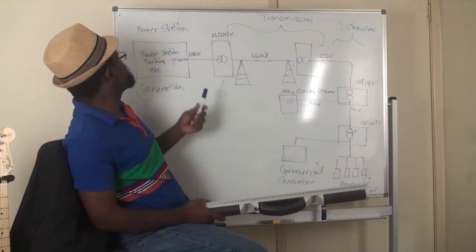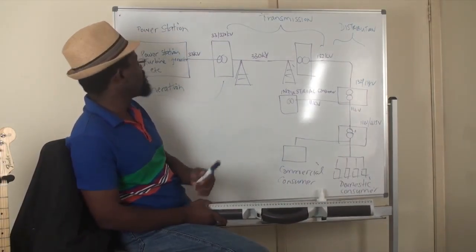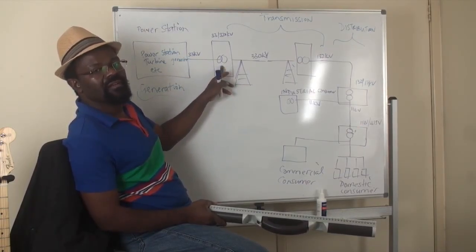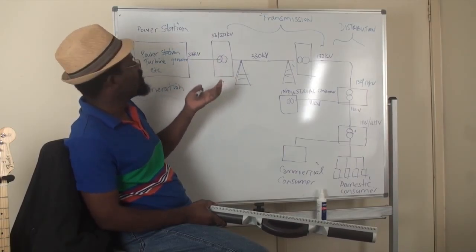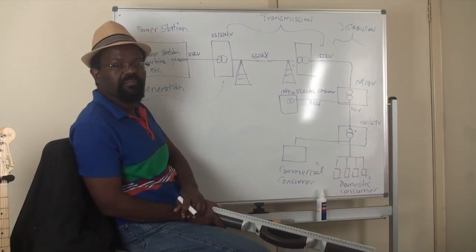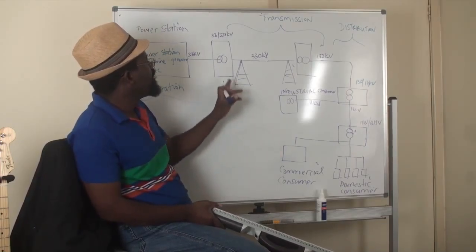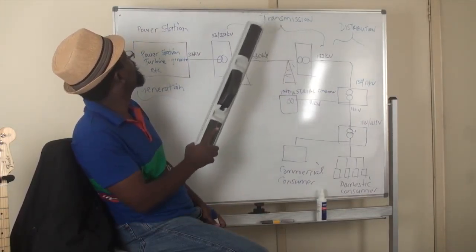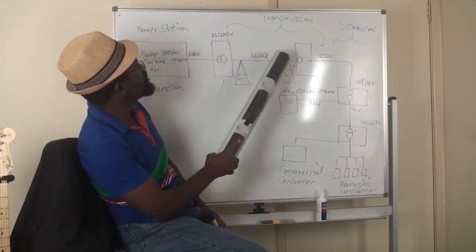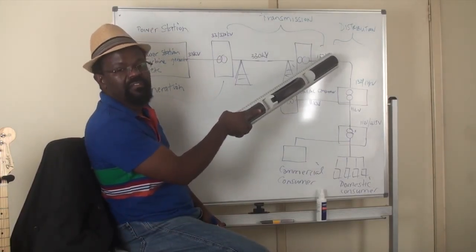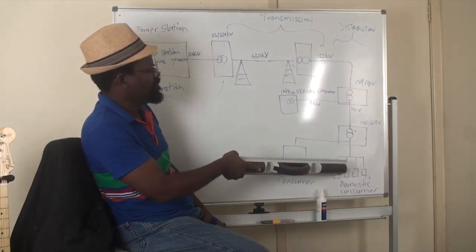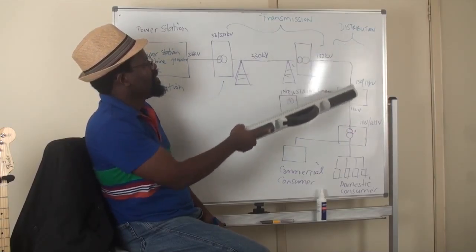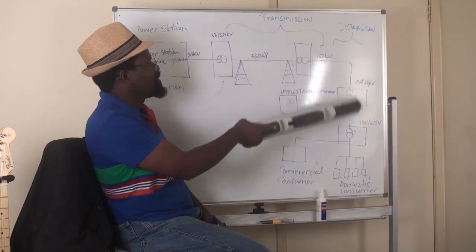So just to give these names, this area where the power is generated is called generation, up to this 33 kV into that transformer there. They have to give each other boundaries according to the policies in the utility. And then these voltages are very high, called transmission. So generation, transmission, and from 132 kV down to 415 volts, it's actually distribution. This whole thing is distribution.